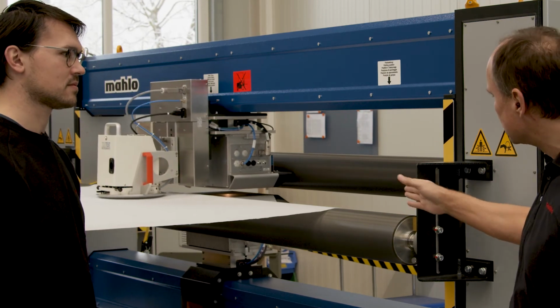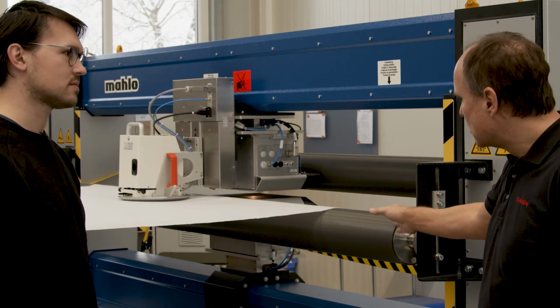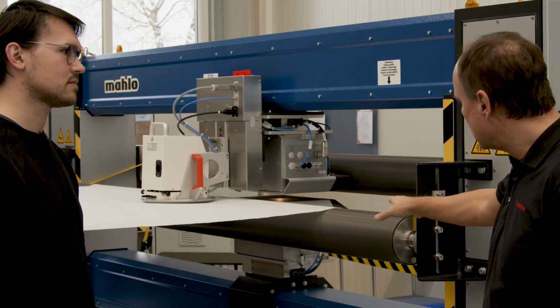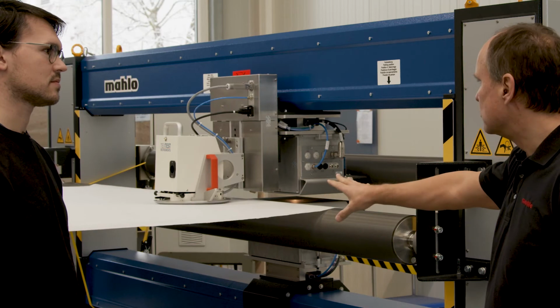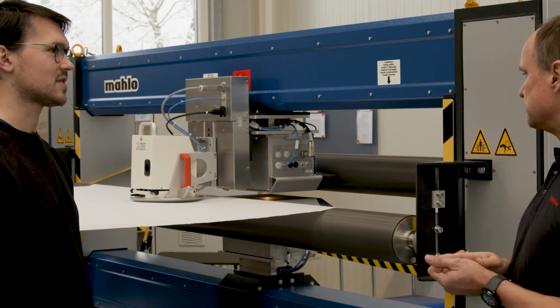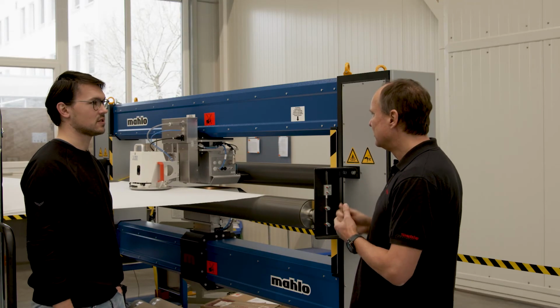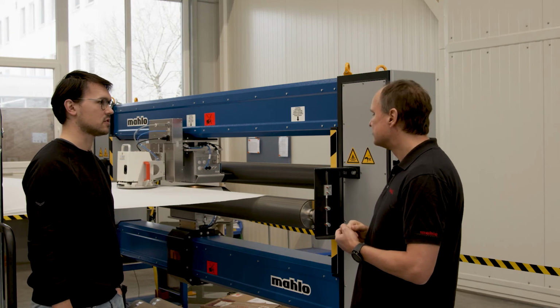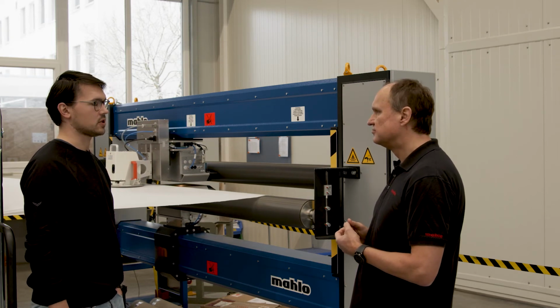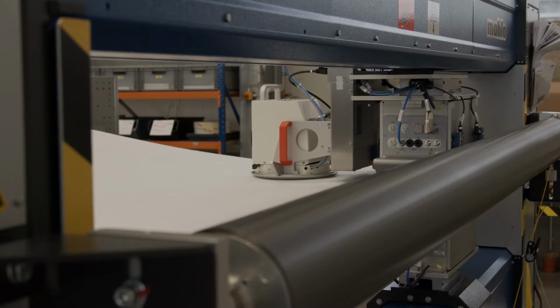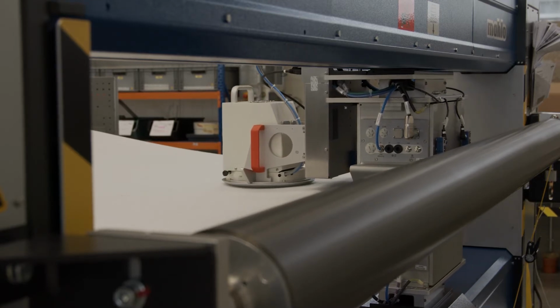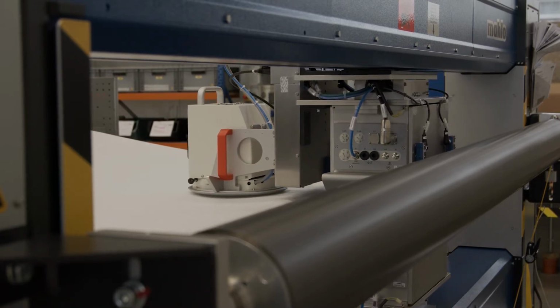And for this reason, we use typically 2 guiding rollers to keep the web in a stable position. That's correct. The web always needs contact to the sensor. If not, we will get a wrong measurement of the air permeability, and that our customer doesn't want.